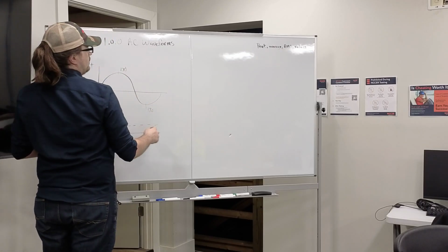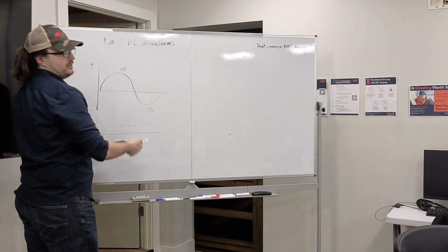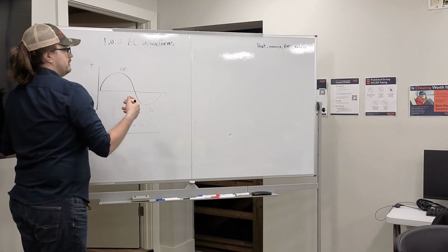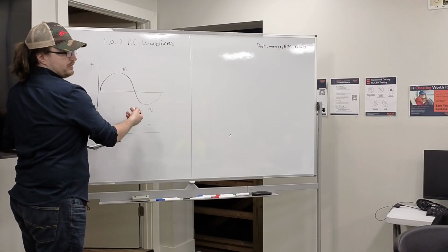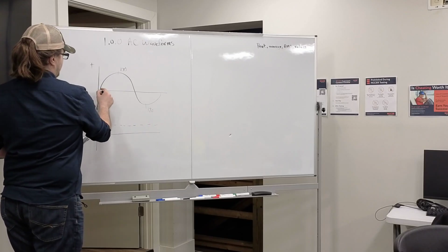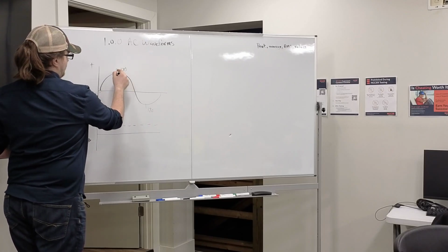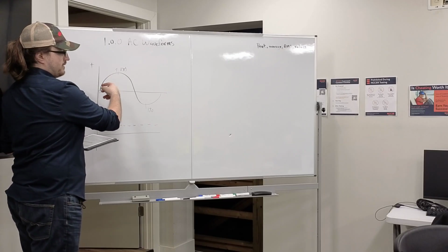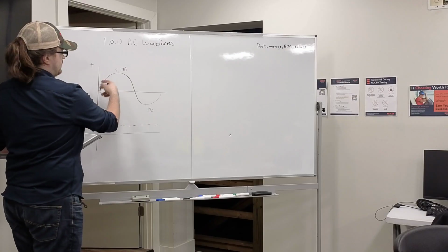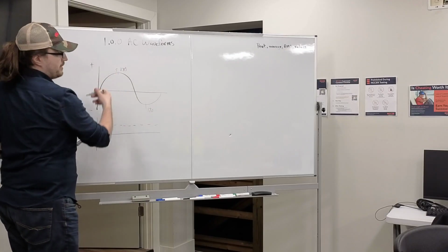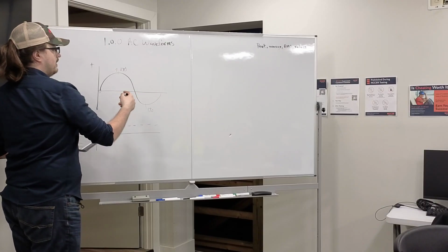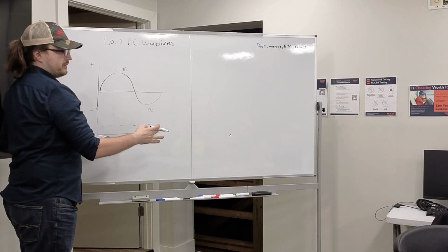Why? Because 120 is the RMS value of 170, root mean square. Meaning, when you take the average of the entire curve, what you get is like it was a point. So like this is 0, this is 1. When you look at it as a product of sine, 0 to 1, and that's no matter what the voltage is, it's always 0 to 1 because sine is always 0 to 1. So then you can take the root mean square of all of them, and it's going to be